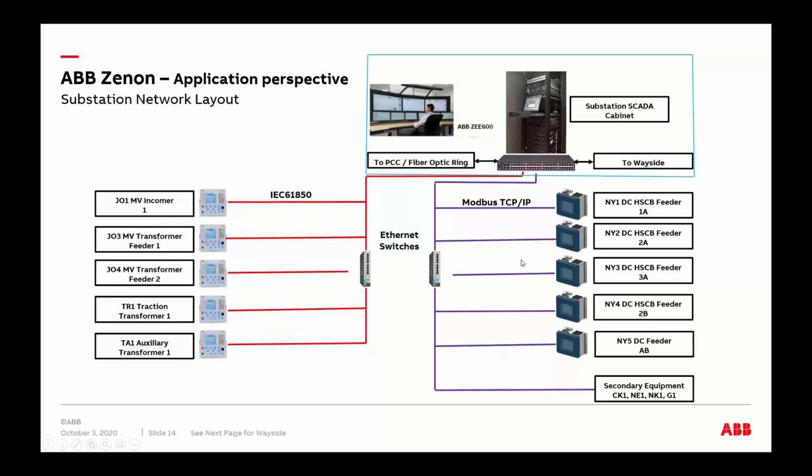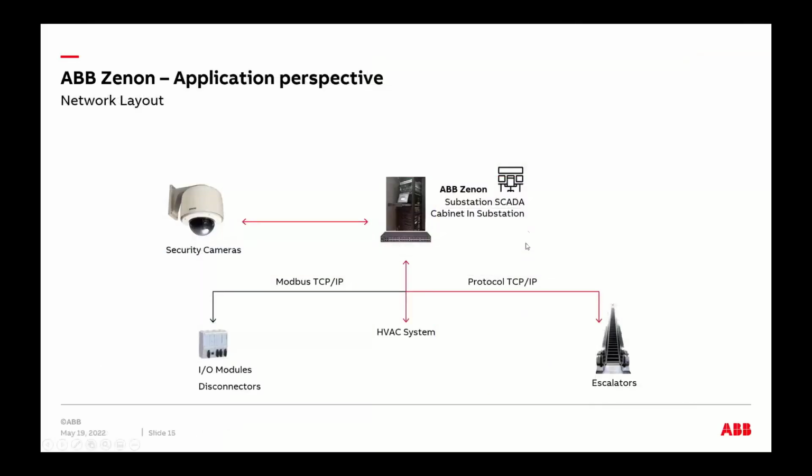So you could see here, we are flexible as far as designing a network. You could do a digitalized one with the normal one, and then you put them together, talking together. Could be maybe substation 2, substation 1, two different protocols. You bring both of them, and then I have a view at my HMI of what's going on with that system. So now you could also do, this is industrial applications, for example, where you have maybe a building that you're trying to monitor. Maybe you have a substation, and also a building that they want to also be part of the digitalized project that you're doing. So flexibility is there. Remember, I'm an HMI. As long as the protocol of that device that I'm pulling the information from is not some exotic protocol, I can do it.